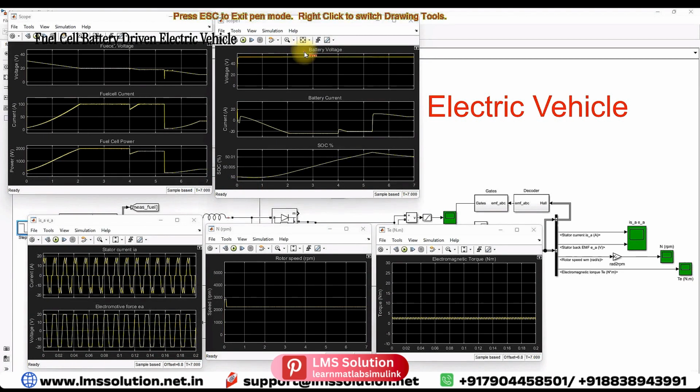During that time, what happens? The battery changes from charging mode to discharging mode. Now the current will change from negative to positive. Positive means discharging mode, and negative means charging mode. Here you will see the jump in battery current from this point to this point because the fuel cell pressure is changed to 0 atm.